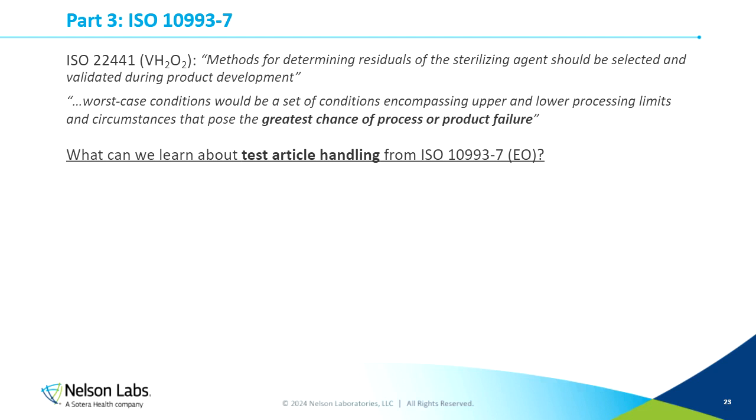So now that we actually know which device we're going to select for testing, how do we need to actually handle this? So the vaporized hydrogen peroxide standard outlines that worst case conditions would be a set of conditions encompassing the upper and lower processing limits that pose the greatest chance of process or product failure. From this statement, you should consider that whatever cycle parameters you use to sterilize these test articles should be justifiable as the worst case scenario for condensing the most amount of hydrogen peroxide on the device.